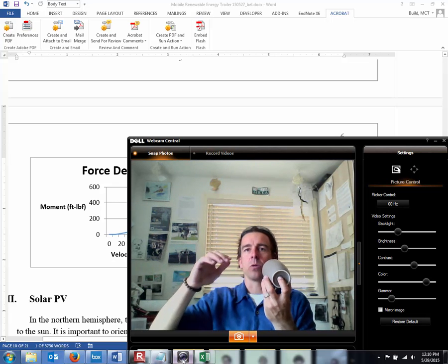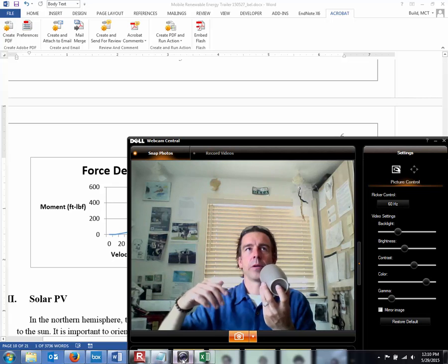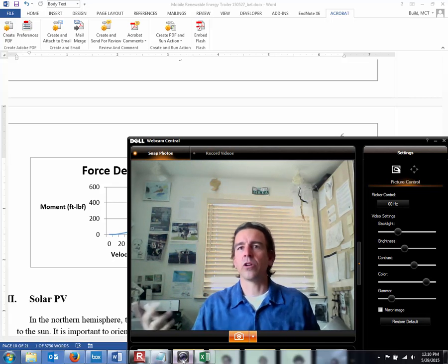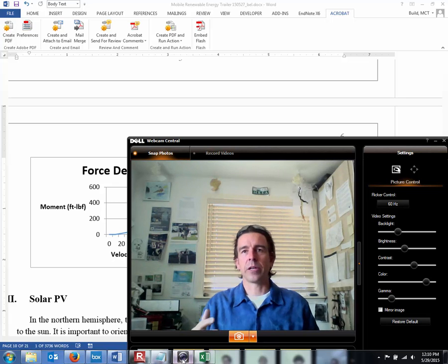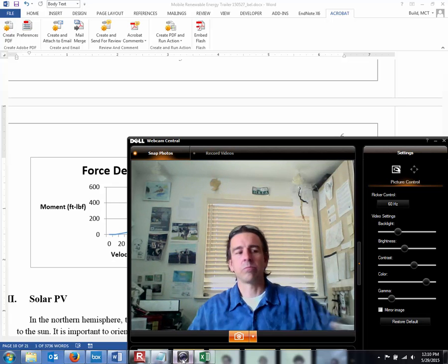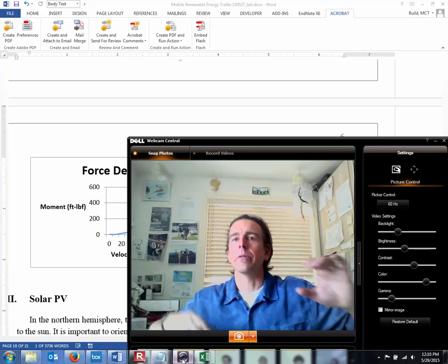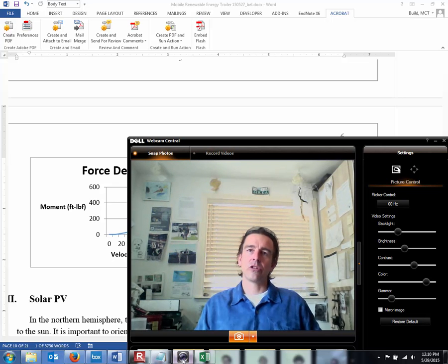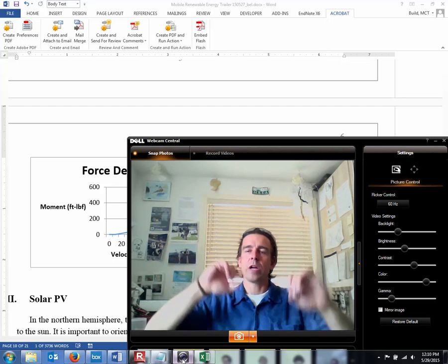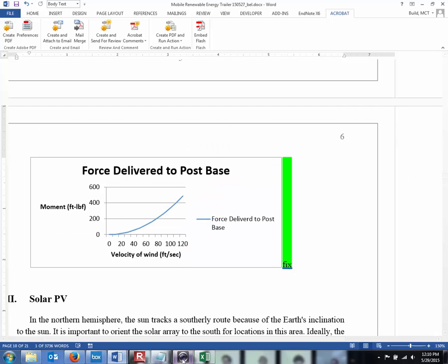So that's torque. You could think of that as just gears. That's why you have gears in a car, because your engine's going to only make so much torque, and in low gear you're going to want a bigger sprocket in the back. So just think bicycle. The force is whatever tension is in that chain, and then the torque is that tension multiplied by the radius of the gear. Oh, okay. Yeah. So fix that.